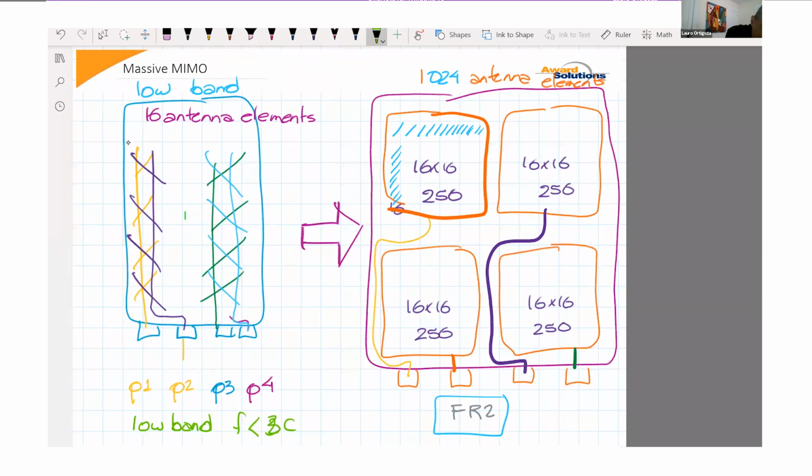So when you think about this, if I want to put antenna elements in a radome, maybe I can only put 4, and more than likely they will be the size of that door back there, right? So there are huge radomes at 1 gigahertz, and they get bigger at 700 or 600 megahertz. So as you can see, I cannot put that many antenna elements there. So there you go, right? In low bands, we have to have these giant radomes, and they typically do not contain that many antenna elements. However, as we increase the frequencies of operation, my lambda decreases.